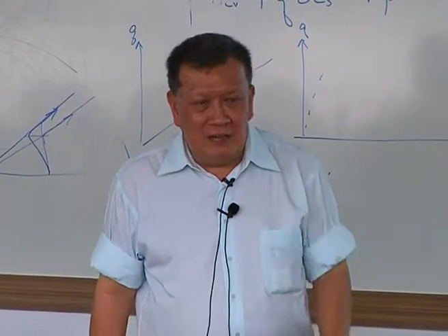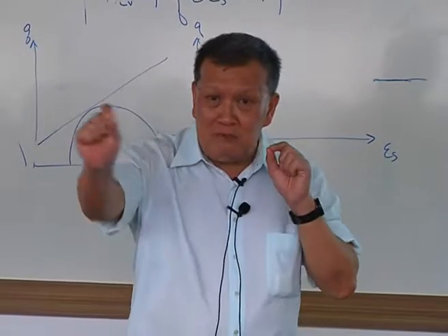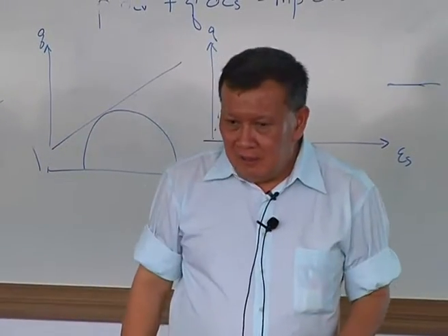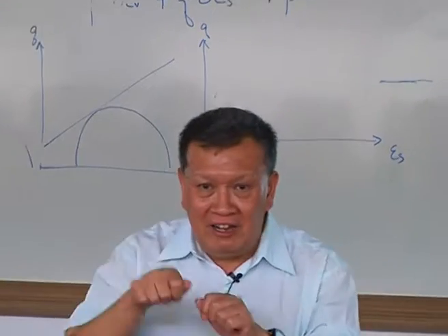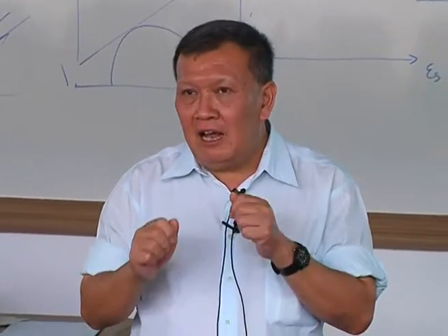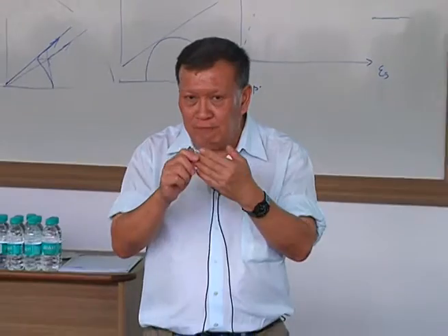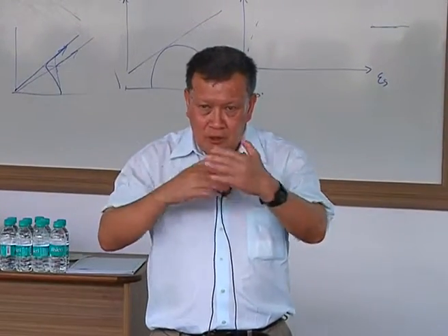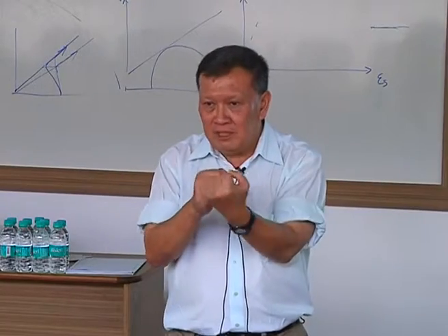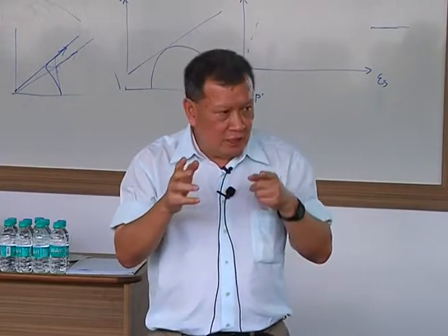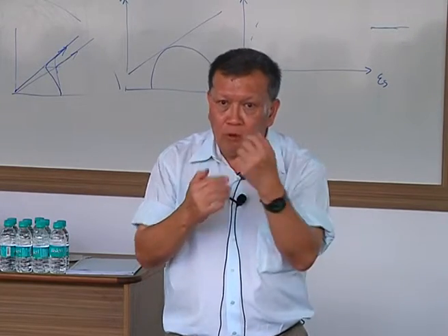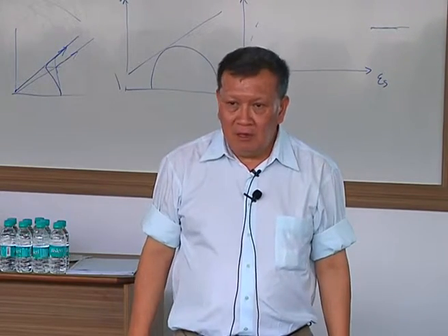Anchor will be less likely. I tell you why. Because anchor has a lower stiffness. So if the wall, anchor, you're talking about ground anchors, right? Okay, anchors are less stiff. Struts are more stiff because they're bigger section, shorter. So all in all, it makes their stiffness higher. Now, a system with a high stiffness, when you subject it to movement, the load will release faster. The load will release faster.